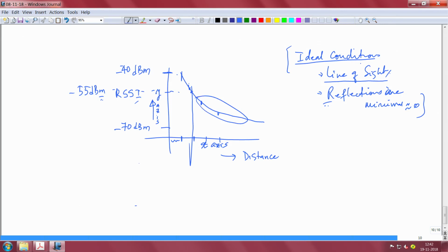RSSI is almost impossible to be used, okay, because if it is mapping here, let us say this is all your 1 meter business, okay. This is between 1 to 2 meters, okay. Beyond this is all more than 2 meters, okay. If it is greater than 2 meters, then you obviously have a problem that this picture cannot be used anymore, and this is reality.